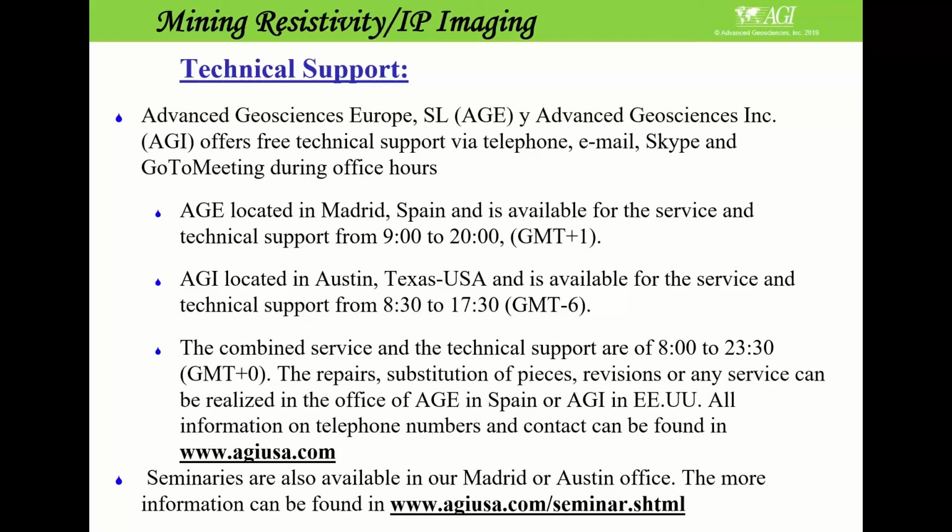Sometimes you really get lots of repetitions, maybe 3 meters in clay, and then 2 meters in coal, and then 1-2 meters in sand, and that will repeat. So in such cases, maybe it is not easy to identify that thin layer of coal, which is typically organic material and will give you high resistive areas in the places.